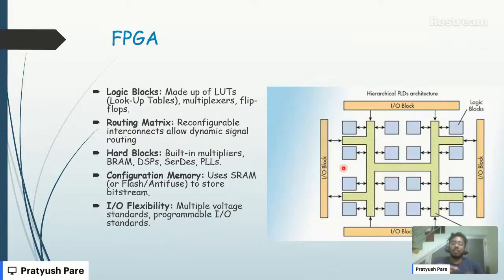In synthesis, it will get converted into some multiplier logic. But if you have built-in multipliers, the FPGA synthesis tool will map those multipliers to the built-in multiplier block. It won't use up any logic block, and that in turn will save memory and leave the FPGA more open to the user for using the logic blocks for different purposes.